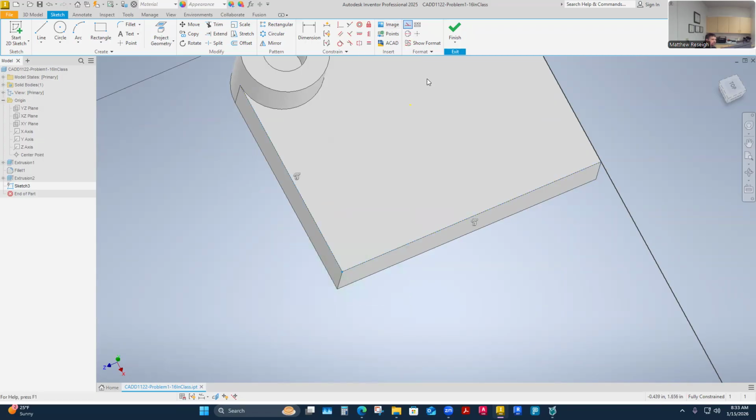A lot of people will keep these as solid, and you can, but eventually when you project and then I draw new geometry, new polygons, if my projected geometry is solid lines, it'll cut across my other maybe closed polygons. And so when I go to actually extrude, I showed a couple people this too, the only reason is I'm simplifying the profiles that I pick when I extrude. If I have solid lines, they'll cut up my profiles sometimes. And it still isn't the end of the world. Even if you have a projected line that cuts through your sketch material, it's just going to chop it up to where you have to do multiple selections to extrude sometimes, and that's not the end of the world, by the way.